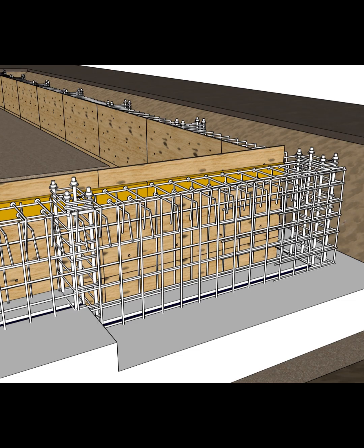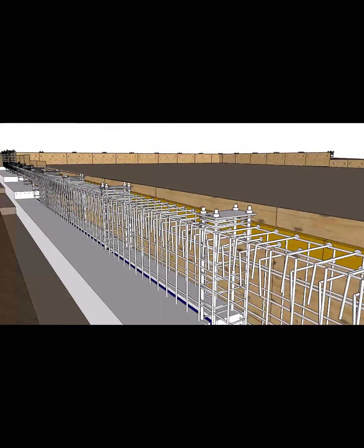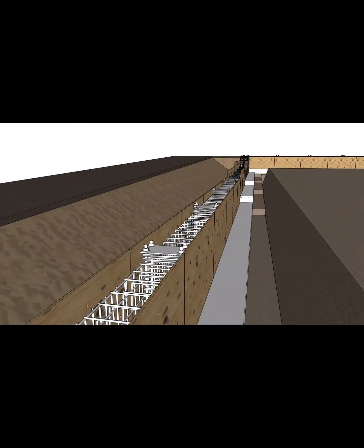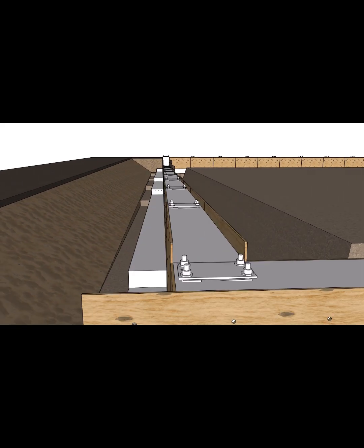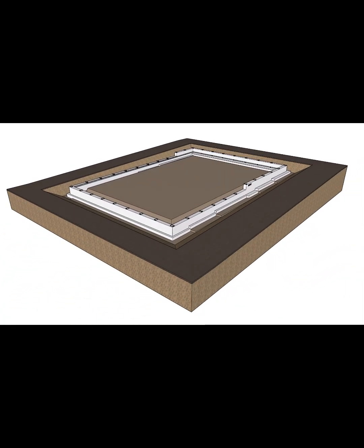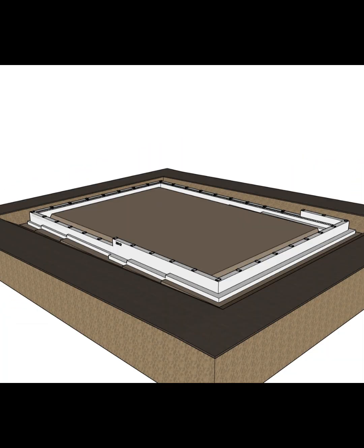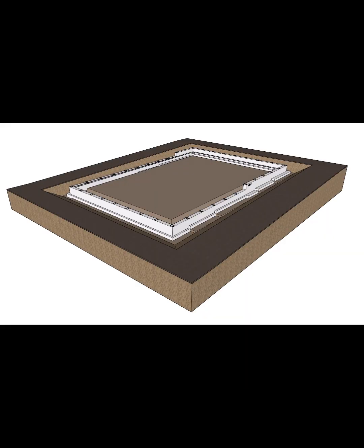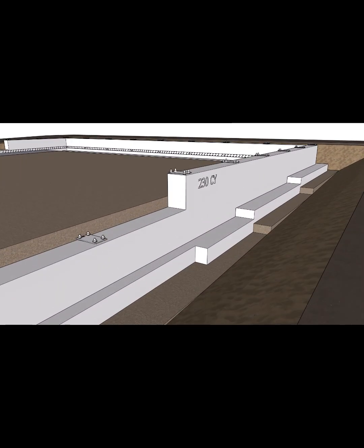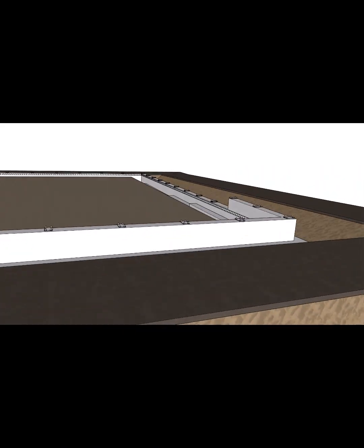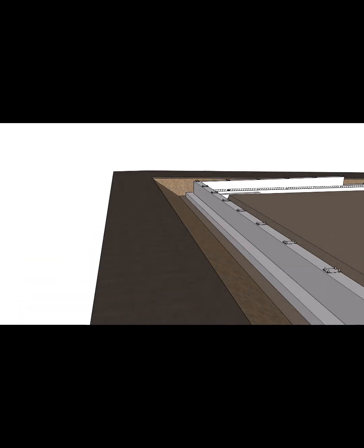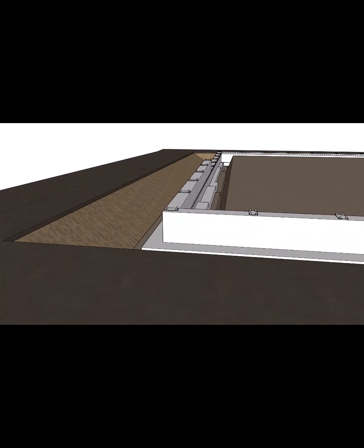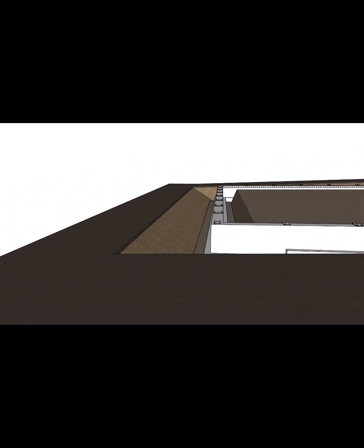Rod busters install the balance of the rebar for the walls. Get the rebar inspection and set the exterior wall forms. Install chamfer at height and place the concrete. Strip the keyways at the form savers and clear out for backfill. The excavation company will be backfilling the interior after the plumbing contractor completes roughing in the drain pipes and chiller pipes. Also, the electrician and security underground conduits need to be completed. Once inspected, the backfill will be compacted and tested.